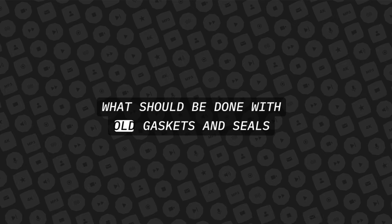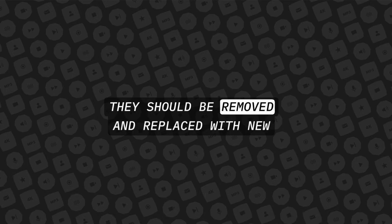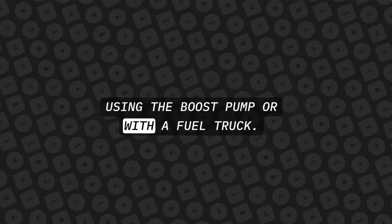What should be done with old gaskets and seals when replacing fuel system components? They should be removed and replaced with new ones. How should you store a bladder type fuel tank? With a coat of oil inside to prevent deterioration. Name 2 ways to defuel an airplane. Using the boost pump or with a fuel truck.